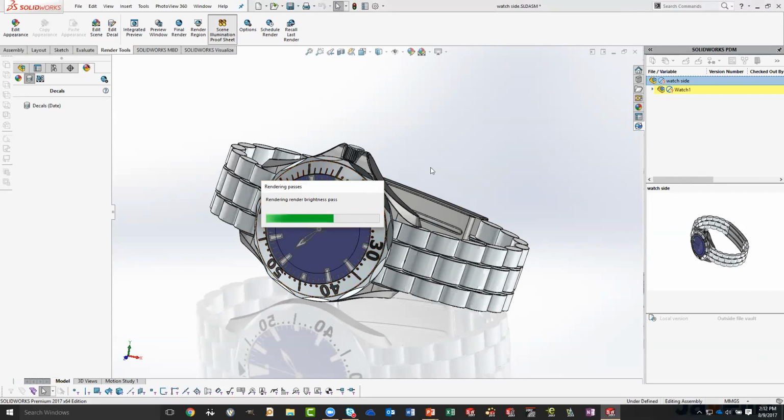that works out as well, we also have render regions. I'm not sure you guys have ever used them before, but if you only want to render a small portion of the actual screen, we can apply a render region, and we can do the integrated display just to make sure that our materials are looking the way that we want them to look before we actually do the render. So instead of rendering the entire canvas or the entire design area, we can render one spot to make sure that it's how we want it to look before we actually go through the entire final render.